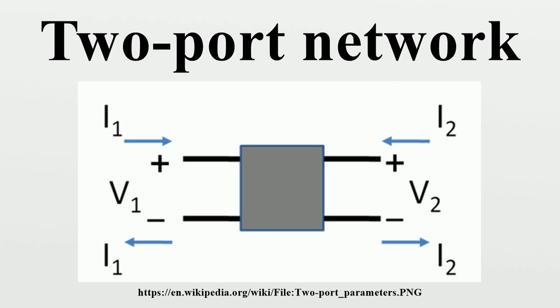T parameters, like ABCD parameters, can also be called transmission parameters. The definition is, T parameters are not so easy to measure directly, unlike S parameters. However, S parameters are easily converted to T parameters. See main article for details.